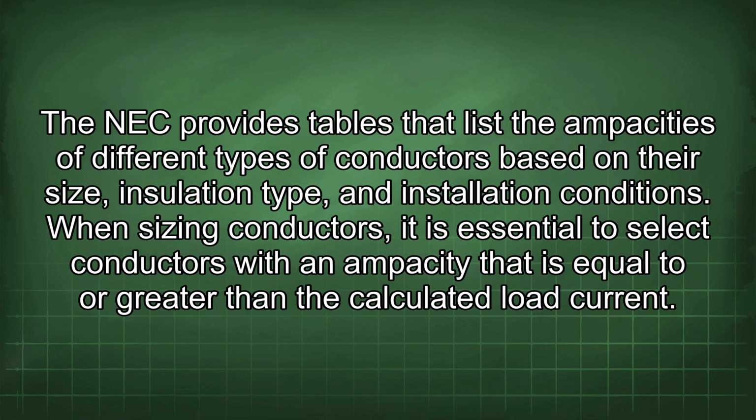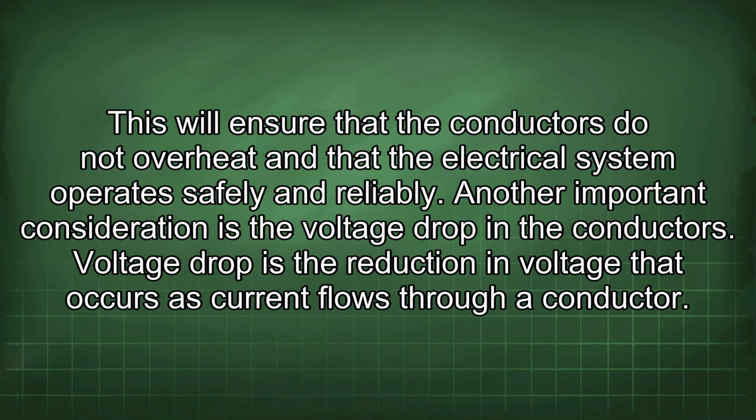installation conditions. When sizing conductors, it is essential to select conductors with an ampacity that is equal to or greater than the calculated load current. This will ensure that the conductors do not overheat and that the electrical system operates safely and reliably.